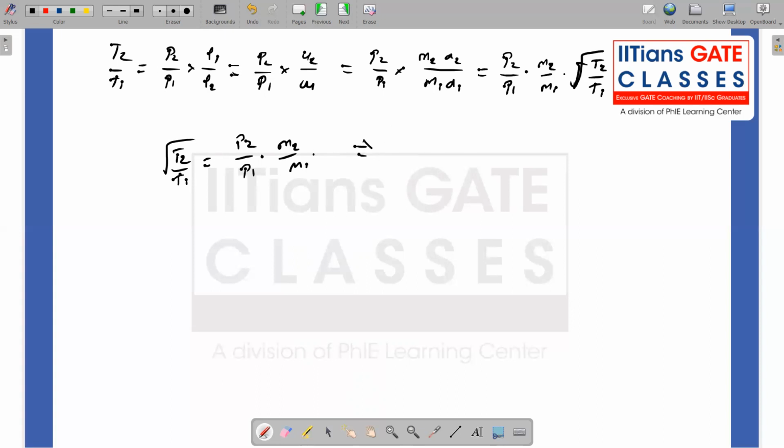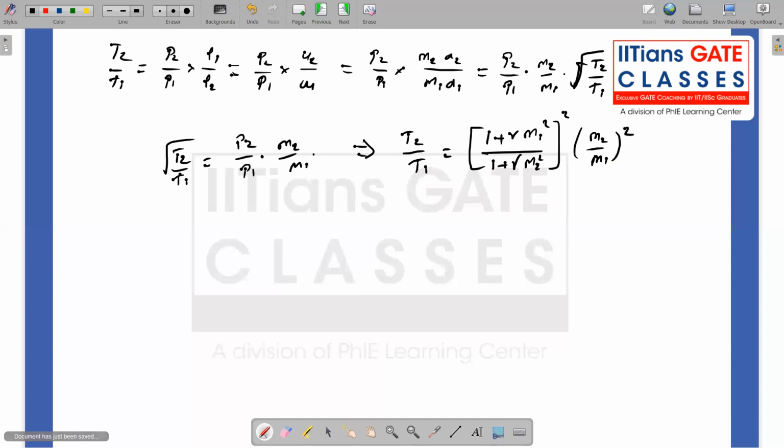So what you get is T2 by T1 is equal to P2 by P1 whole square. We already solved for it: 1 plus gamma M1 square divided by 1 plus gamma M2 square, the whole square, squaring both sides, times M2 by M1 whole square. So this is T2 by T1.